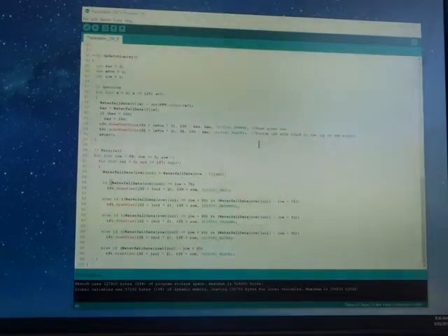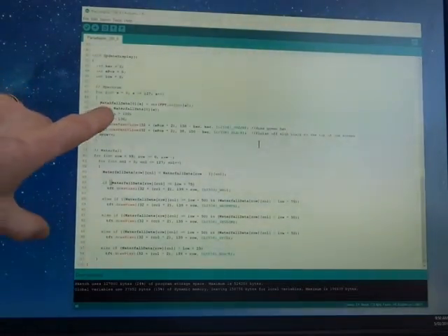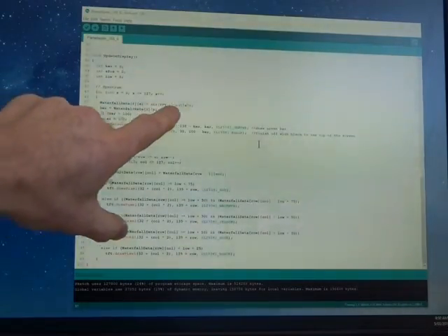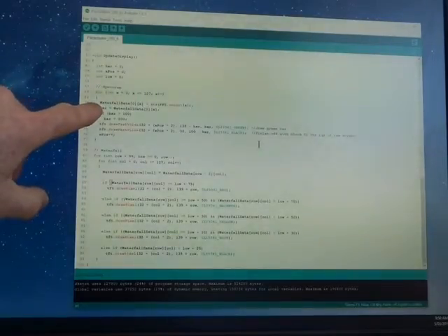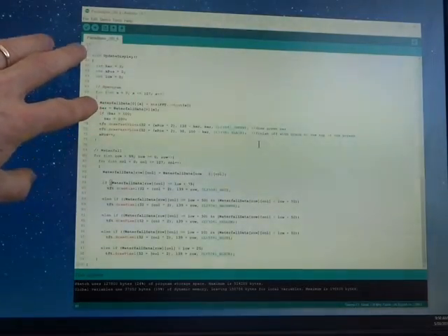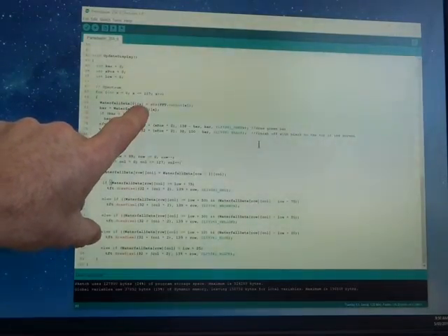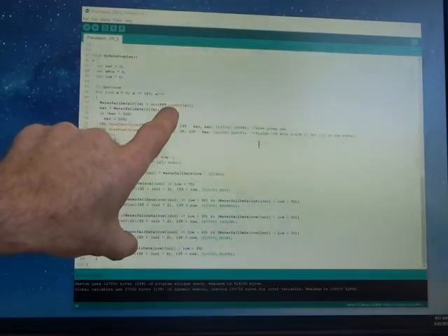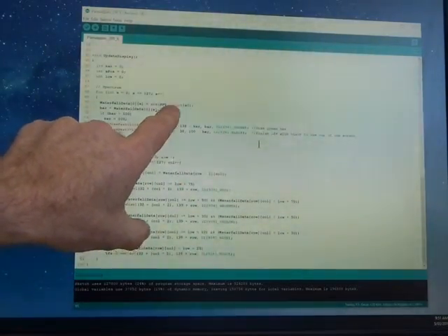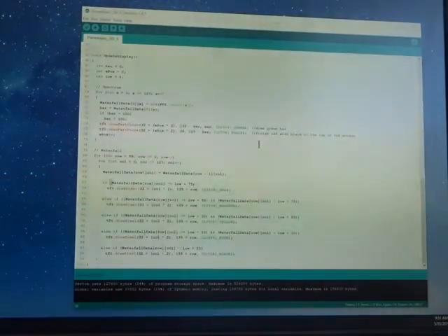The first portion is to do the spectrum. First I populate the very top row of that waterfall data array. You can see I'm populating row 0, the uppermost row, and I'm running through each of the 128 bins and populating it with the output of the FFT, again for each of those 0 to 127 bins.